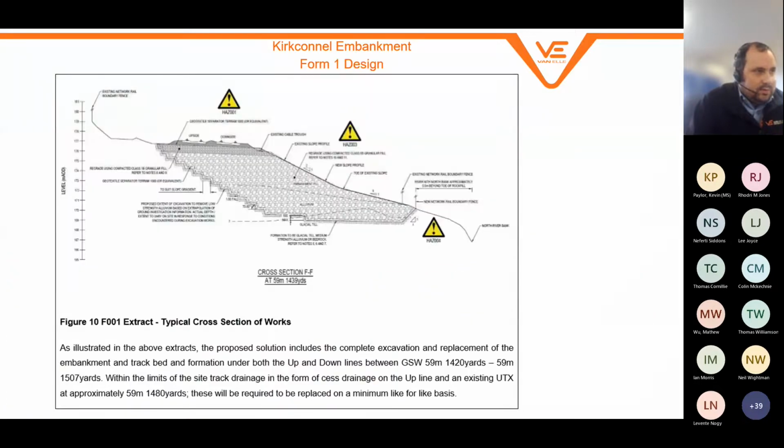So solutions were looked at. Our client QTS got us on board, so they were looking at doing a track out solution. So remove the two existing lines, the up and the down, excavate out the affected material, and reinstate that embankment with an engineered fill.